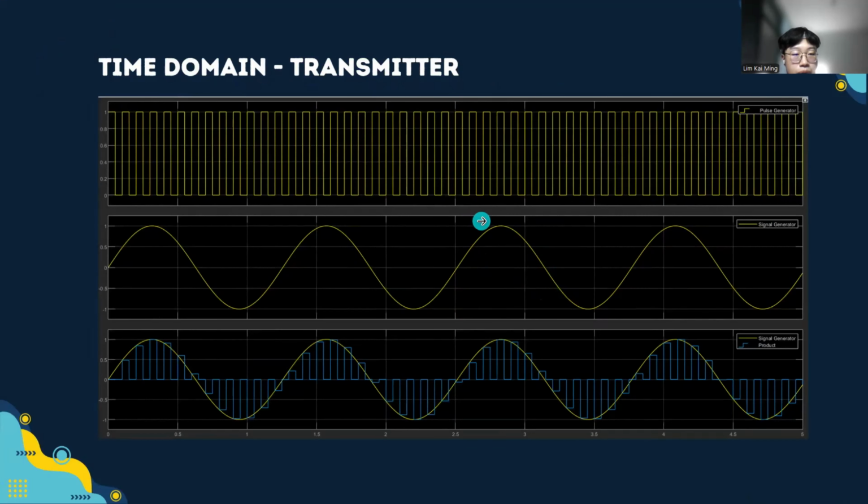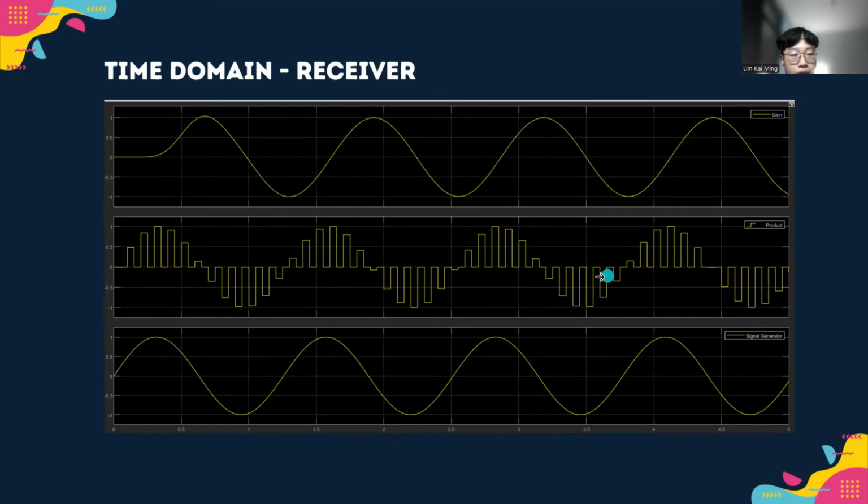In the time domain waveform, the pulses have a constant amplitude during each sampling interval. This makes flat-top PAM more stable and suitable for further digital processing, such as analog to digital conversion. The recovered signal closely resembles the original message signal. Compared to natural PAM, flat-top PAM provides better control over sampling and is less sensitive to timing variation.